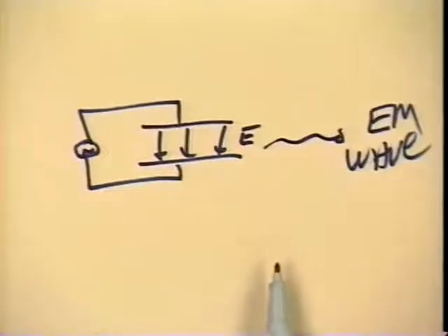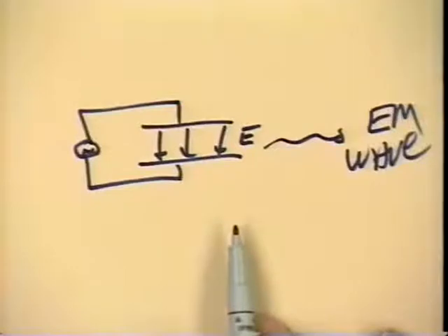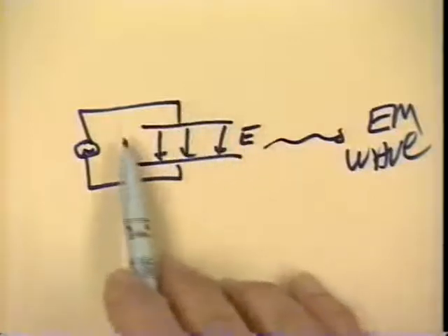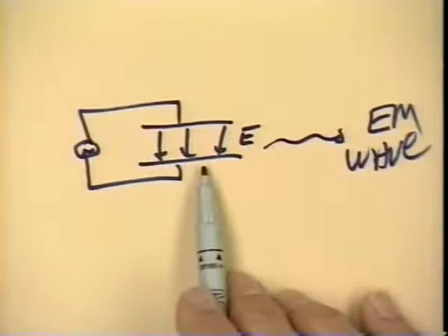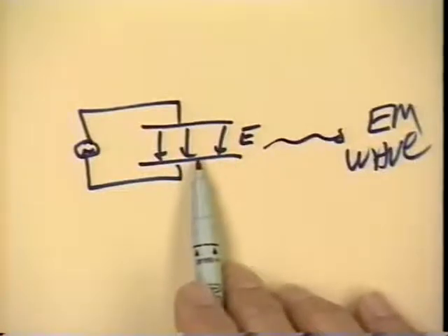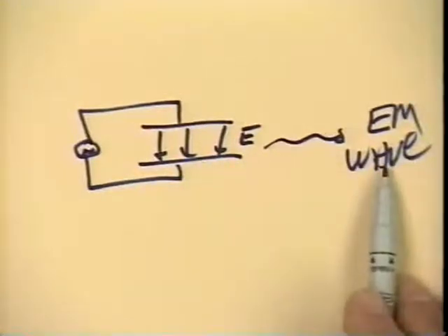So similar to what we had a moment ago with the coil. With the coil, at high frequency we had stored magnetic energy and radiated electromagnetic wave. Now with a dielectric or a dipole-like structure such as the capacitor, we have stored electric energy and at high frequency radiated electromagnetic wave.